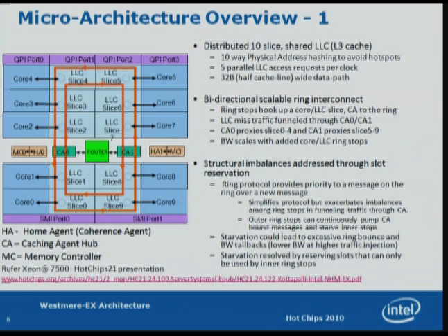It's a highly scalable interconnect, and all through the interconnect, if you can see in the diagram, you do have these ring stops, and these essentially hook up the caching agent or the LLC slice or the core to the ring, right? Now we do have 2 caching agents. It's called CA0 and CA1 in this diagram in the middle, right?